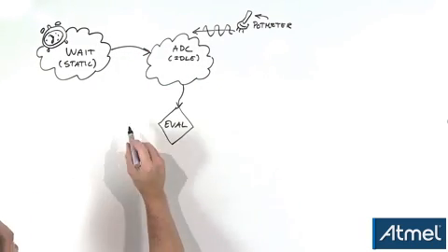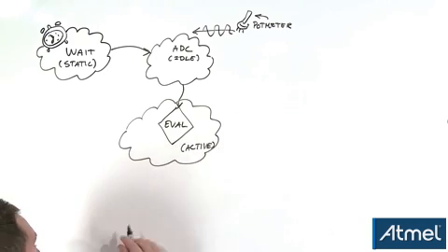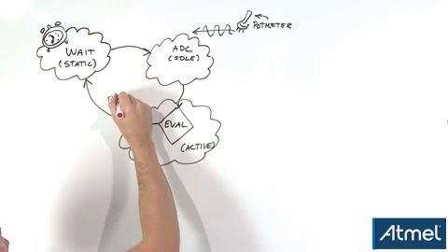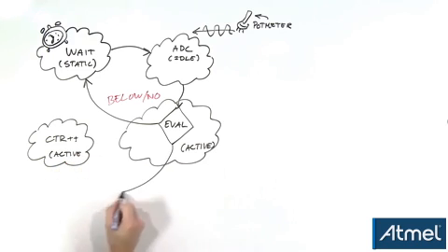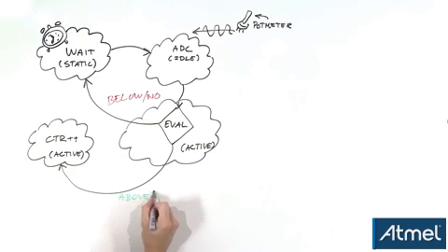So, the ADC takes one sample that the CPU evaluates. If it's below the threshold, we go directly back to static mode. If it's above, the CPU increments the counter before we go back to static mode to wait for the next sample. We do this every 5 milliseconds. Let's look at this in the oscilloscope.